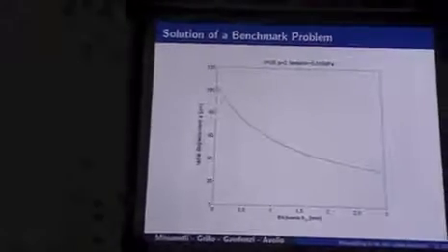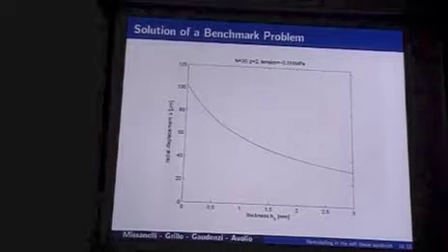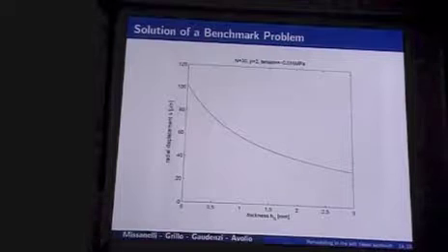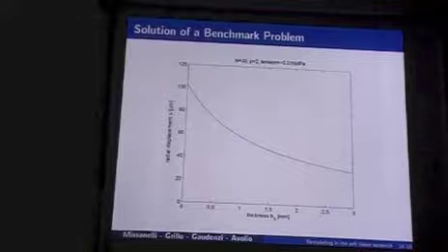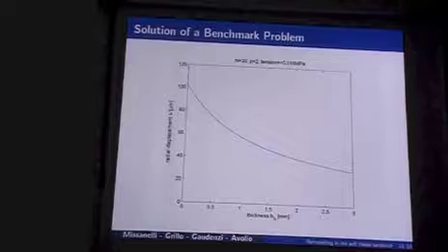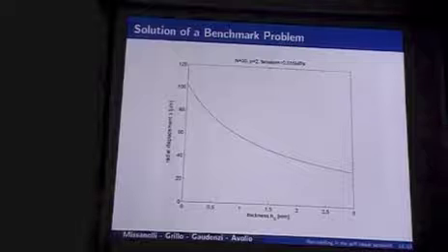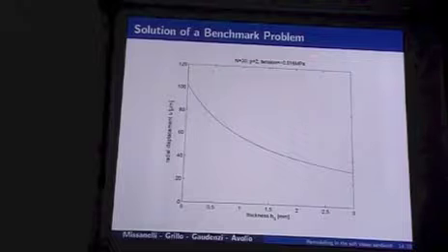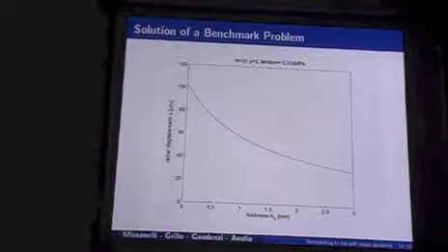Using a finite element implementation in Matlab, we discover this decreasing of displacement along the thickness of the system. And in particular, we get this result, 10 micrometers, that is quite comparable with some other works, for a tension that is systolic pressure, 120 millimeters of mercury.